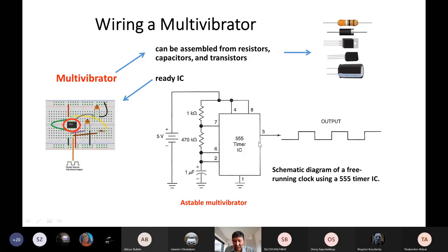The purpose of this course is to know some simple digital systems, how to utilize them and try to assemble them, maybe in a hardware version or in a software simulation environment. So it is the heart of this astable multivibrator, this timer integrated circuit. To start it, we need to wire it with some resistors, give power, and we will get this kind of signal.